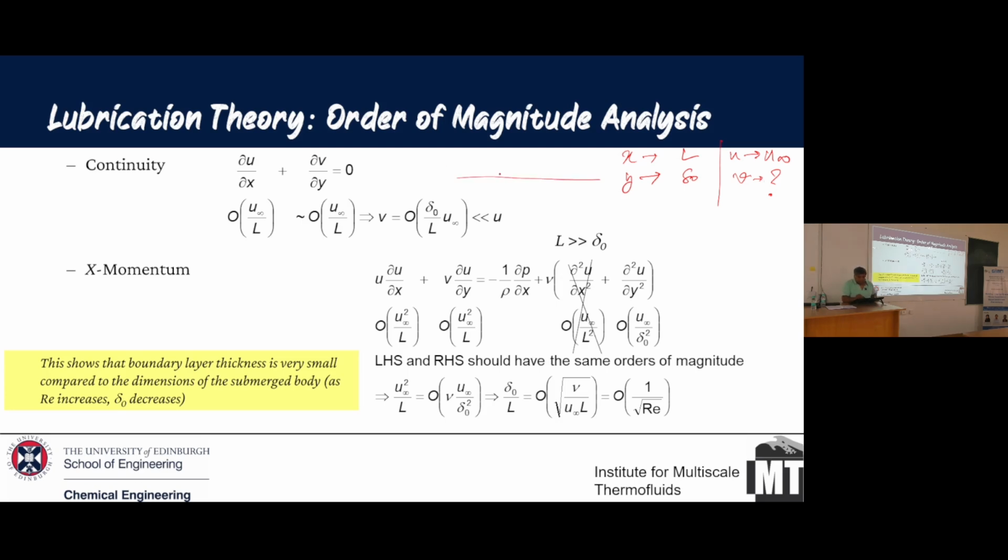So essentially, you have this boundary layer here. This is where you have u and v, and we have no idea what v is. We have some idea what u is. U is more a function of u infinity. We are not terribly worried about that. Okay, but something clearly we are not aware of is v. So what we can do is something called an order of magnitude analysis. So we can say that this one, del u by del x, is something of the order u infinity by L.